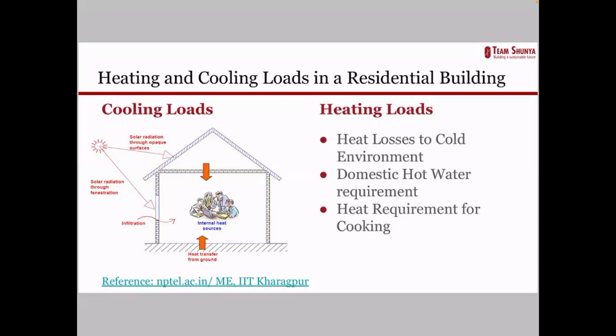And if we consider the internal sources, there are various devices running like lights, electronics, computers, TVs, and those will cause heat addition to the room. Those kinds of loads are called sensible loads. And there is a second kind of load which not only adds temperature rise but also adds moisture rise in the room.